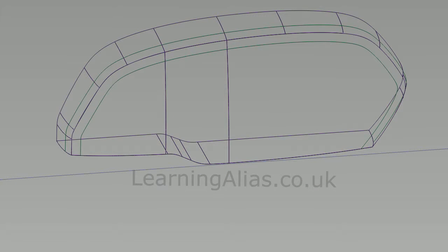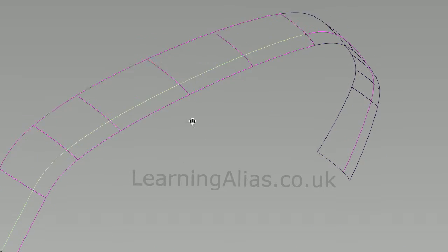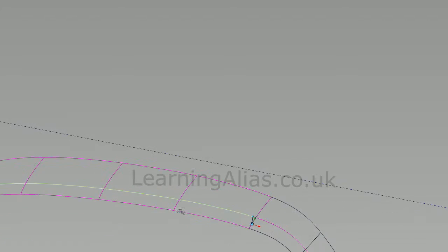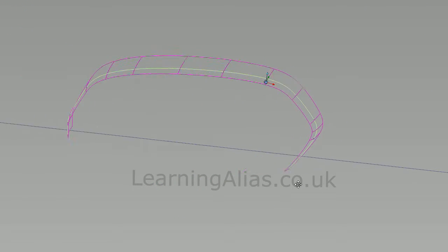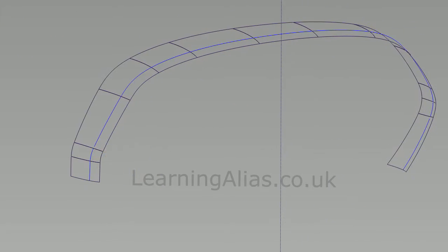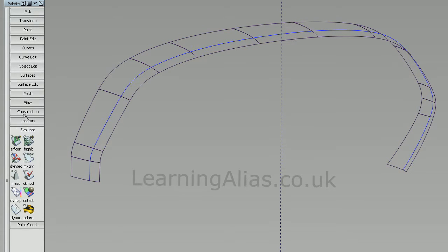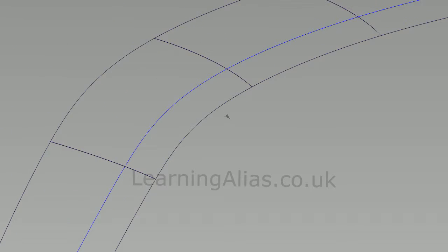So now we need to check on our curves on surface because the tubular offset tool will often leave little sections at the end of your curves on surface which will cause problems later on when building the blend. So I'll go around and select through the center of all of my curves on surface and then drag select everything, and you'll see that I'm just left with the small little sections which we can delete. We can then extend our curves on surface with extrapolate on and merge on, and if I hit Control Alt and snap to this surface boundary, snap to the surface boundary.